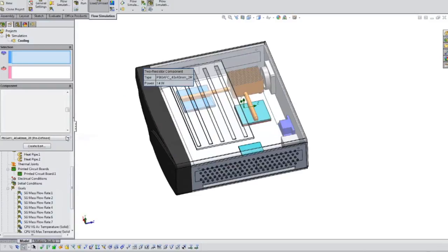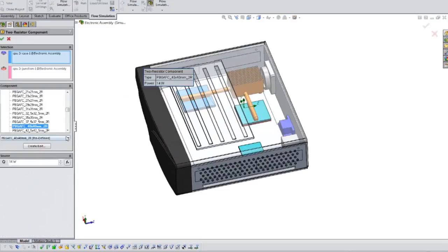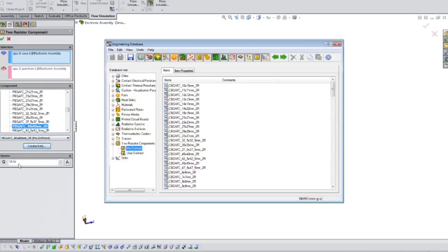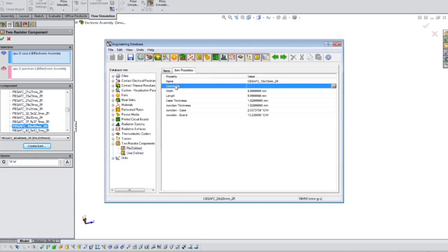So from a SolidWorks modeling perspective, you can imagine your model might look a little bit more complicated than this one. But from taking it from your full-on design for manufacturing and drawings to what you need for SolidWorks Flow Simulation, it's really a matter of just adding a few components to block off where the inlets and outlets are. You can see here, we just put a block on top of these outlets at the top. We put a block on the side ones. Again, we're just trying to tell SolidWorks Flow Simulation that we're doing internal analysis and we really just want the flow to exist inside of the model.